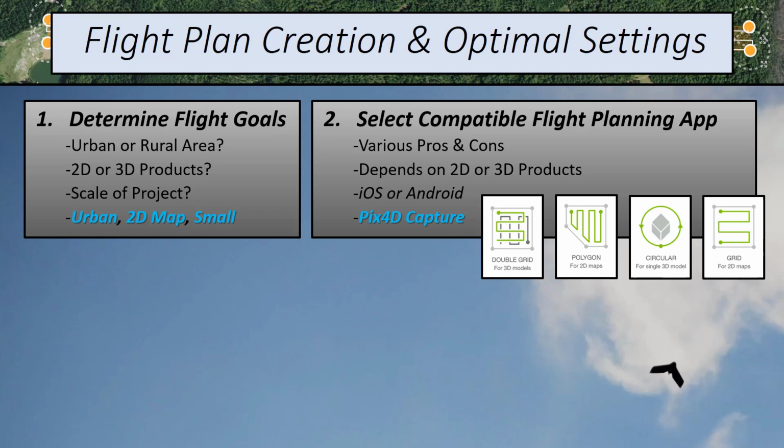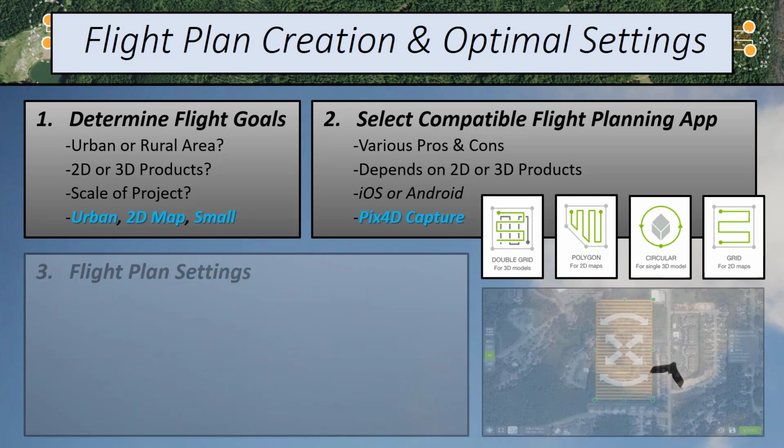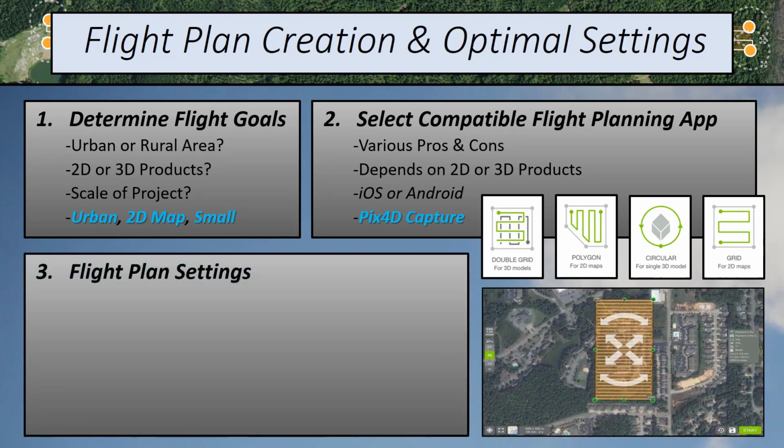Once again, the app that you'll end up using will more than likely depend on whether you need 2D or 3D products. It will also depend on your particular smart device that you plan to use, if it is an iOS device or an Android device. For our example, we elected to use Pix4D Capture to create our flight plan, and we'll be using it on an Apple iPad tablet. Once you have selected your preferred flight planning app, you now need to choose the optimal settings for your flight.